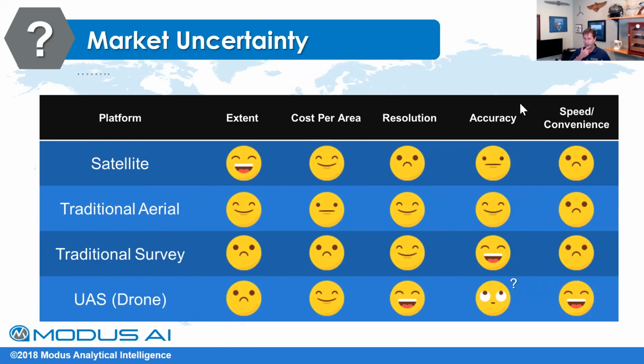The quality level that we get out of there, depending on which satellite and its orbit, you can still get a quality level 1, but you're not going to get much more than that. Part of that resolution problem is that the Earth is covered by 80% clouds, same thing with visual type technologies. So having opportunities where you're not obscured by atmospheric conditions that cause scatter becomes a problem. Then there's accuracy, which you have to go to great lengths to baseline to make sure you're geodetically sound. And of course speed, depending on how many orbits you have, or the periodicity, can be rather difficult if you don't know where you're going.